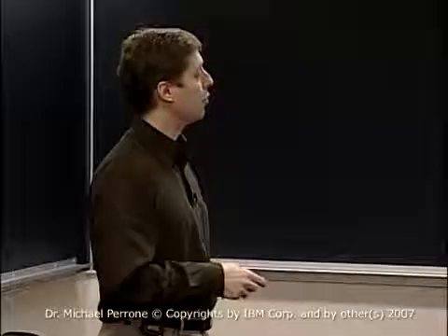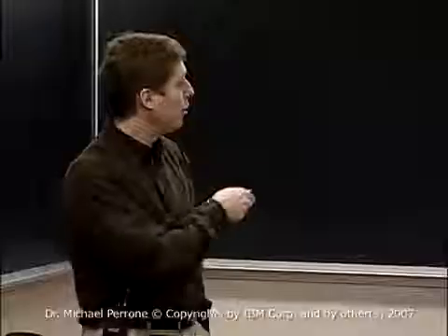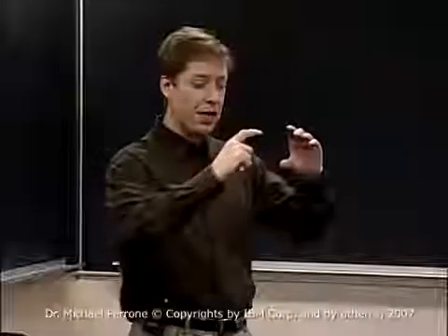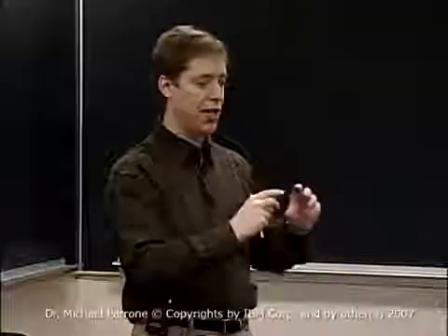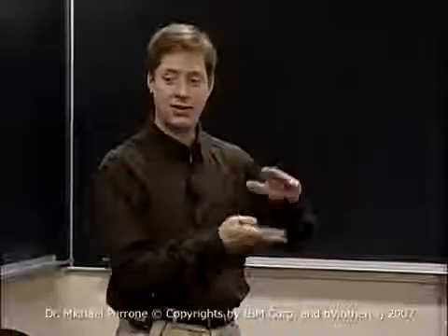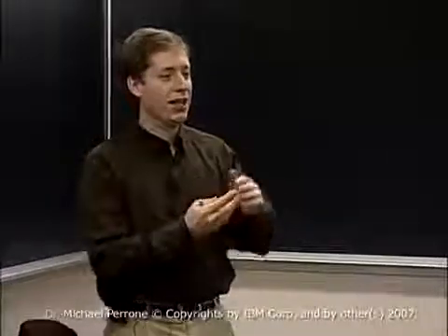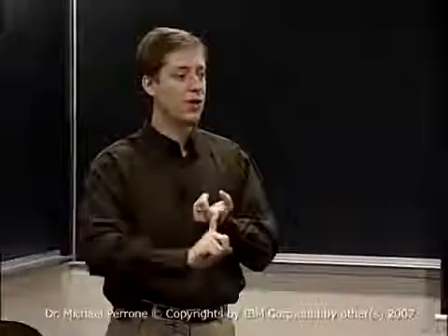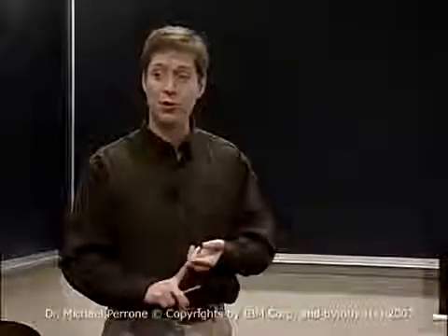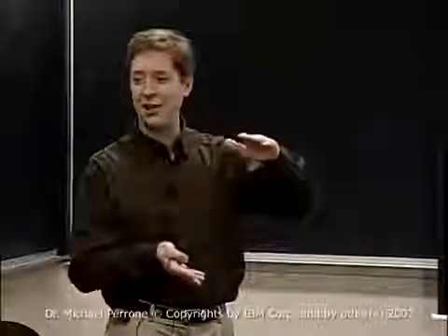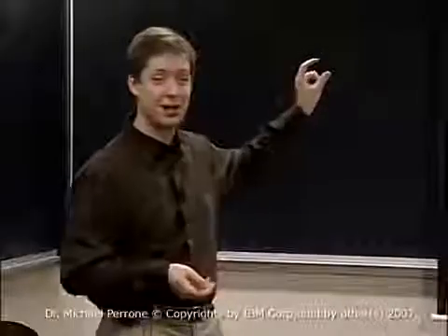Another consideration is this local store, right? Each local store is 256 kilobytes. That's not a lot of space, right? You have to think about how are you going to bring the data in so that the chunks are big enough, but not too big. Because if they're too big, then you won't be able to get multi-buffering, right? So if your data chunk is, well, let's back up a little bit more. The local store holds the data, but it also holds the code that you're running. So if you have 200 kilobytes of code, then you only have 56 kilobytes of data space.